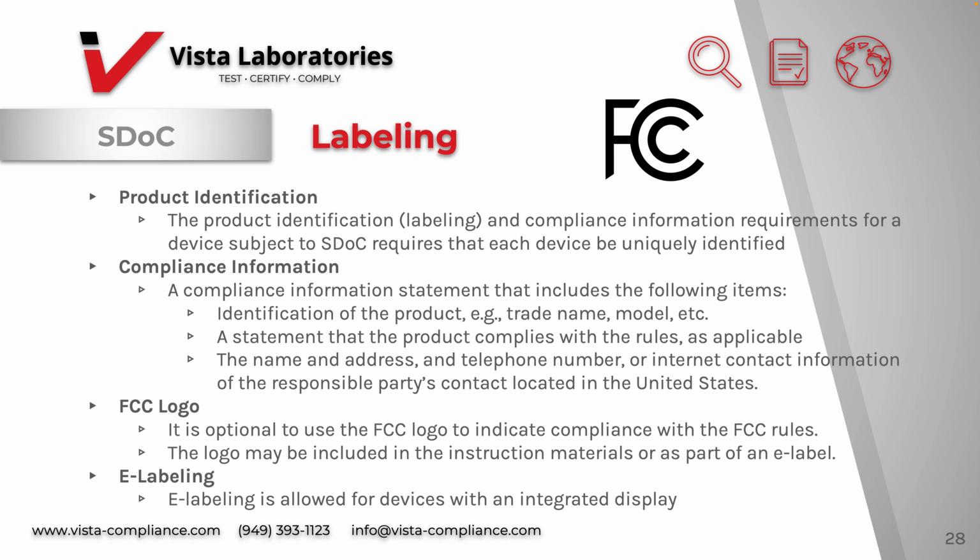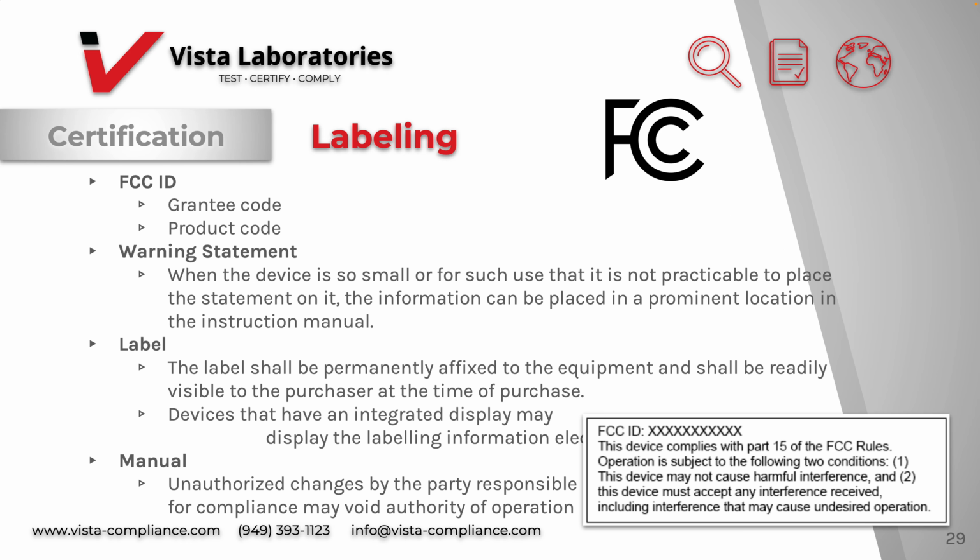E-labeling. E-labeling is allowed for devices with an integrated display. Certification labeling. FCC ID, grantee code, product code. Warning statement. When the device is so small for such use that it is not practical to place the statement on it, the information can be placed in a prominent location in the instruction manual. Label. The label shall be permanently affixed to the equipment and shall be readily visible to the purchaser at the time of purchase. Devices that have an integrated display may display the labeling information elsewhere.